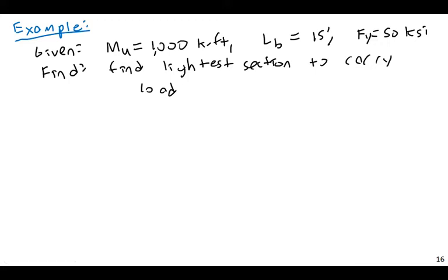So now let's see here. We need to find a section to carry this load. Let me find the citation in the manual, phi MP of 1,060.